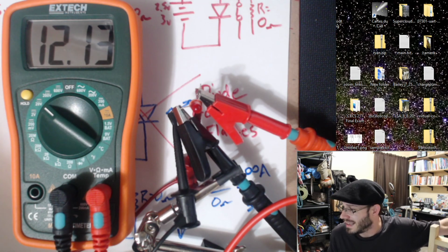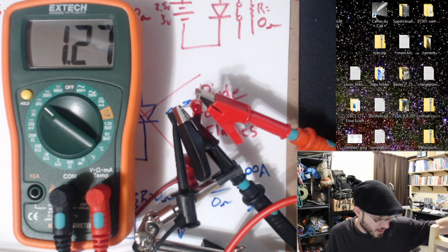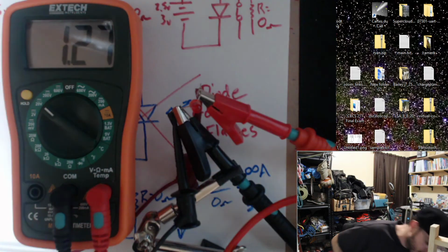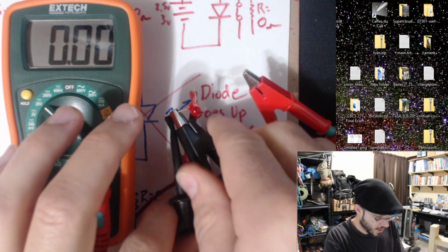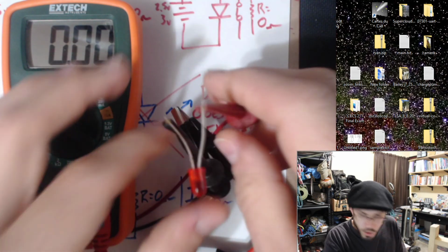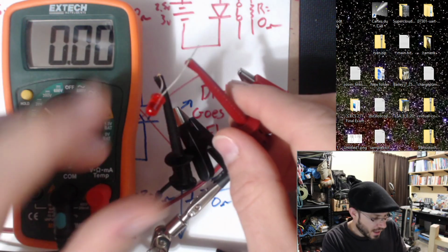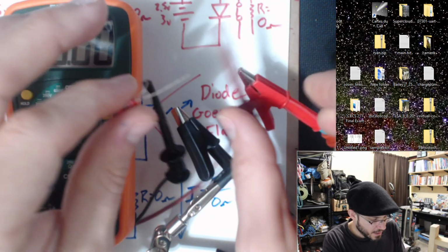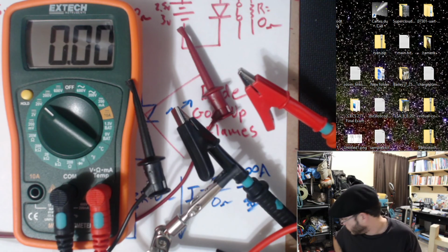What happens if I touch it? Well, I'll probably burn myself. What's the average lifespan of a diode LED? It can be a very, very long time. Okay. Oh, yeah, that smells awful. Oh, okay, good. I did not burn my expensive connectors over here. So this diode, word of advice, when you burn out a component like this, throw it away. Don't put it back into your parts bin. If you put it back into your parts bin, it just guarantees that you're going to use a bad diode at some point in the future. So into the trash with this guy.